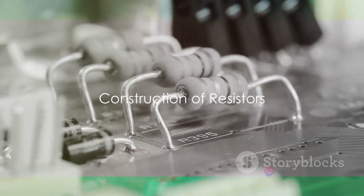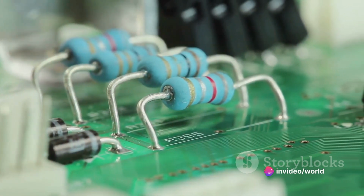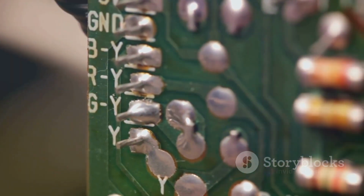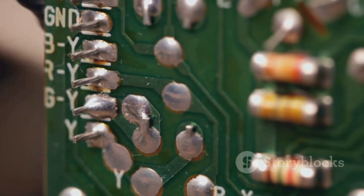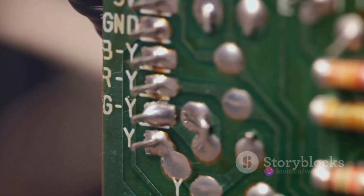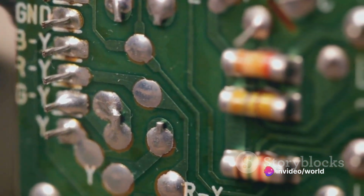Now let's delve into the construction of resistors. Most resistors are made of metal oxide film, metal film, or carbon film. The resistance value of a resistor depends on the type of material used, its length, and its cross-sectional area. The longer the resistor, or the smaller its cross-sectional area, the higher the resistance.